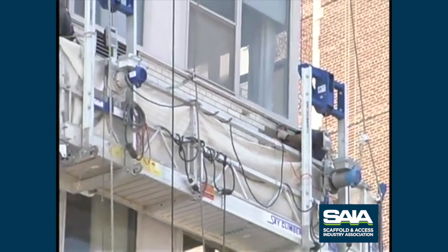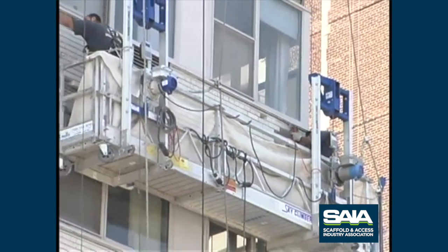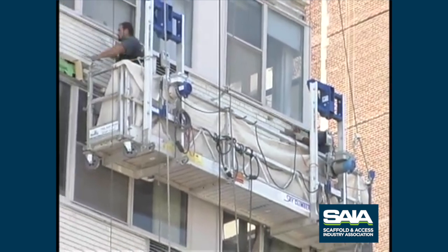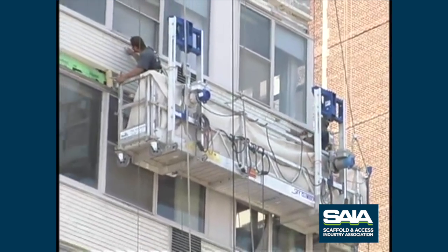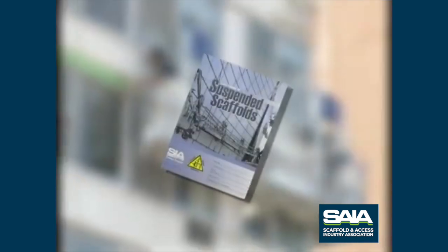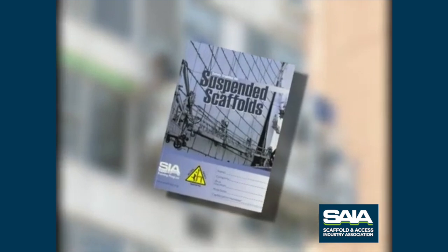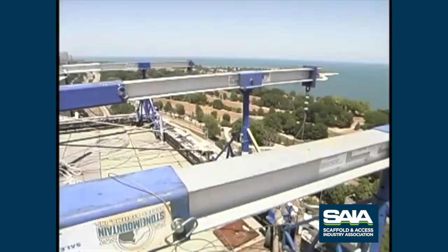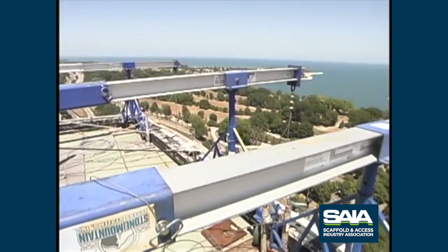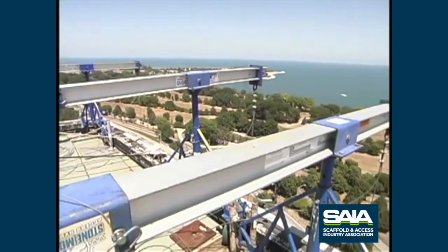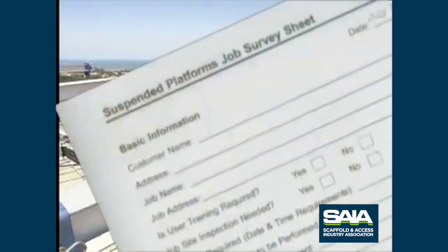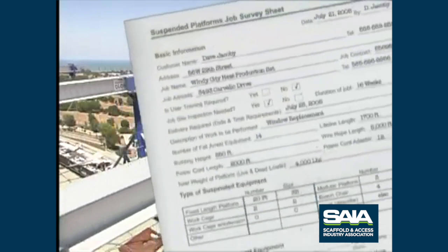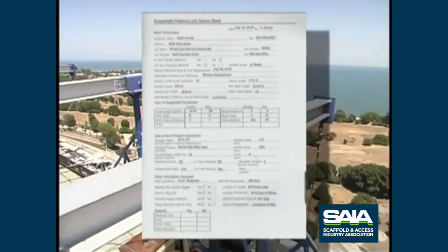Only workers who have been instructed in the operation, use, and inspection shall operate the suspended scaffold or controlled descent equipment. The SAIA Suspended Scaffold Training Program provides these instructions. A qualified person must develop a plan for installation and relocation of suspended access equipment. Refer to the SAIA Job Hazard Checklist for suspended scaffolds for assistance.